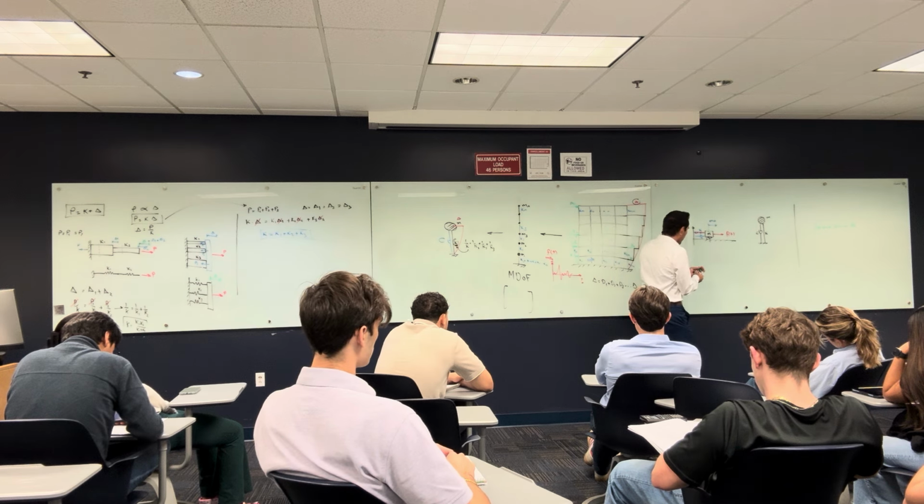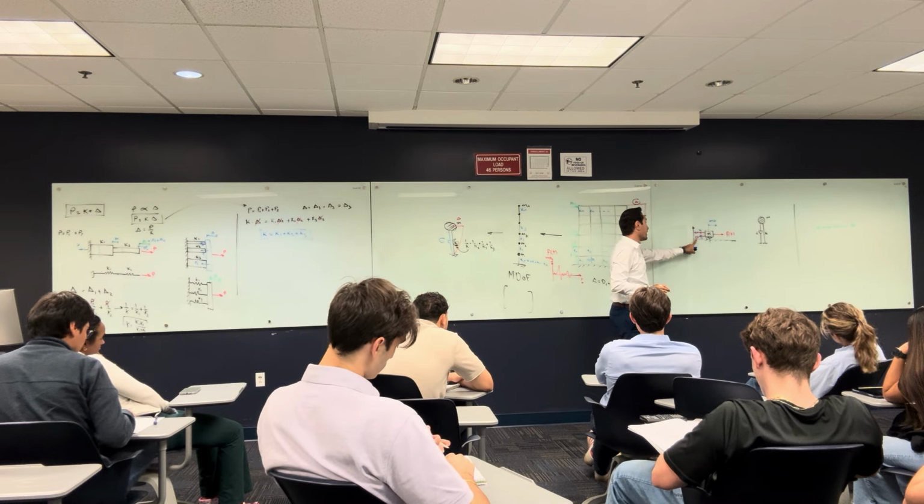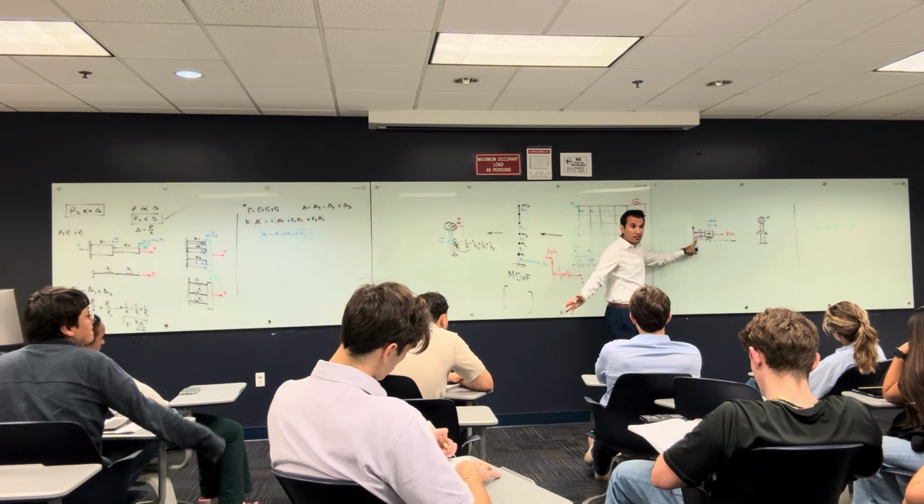The damping coefficient is gonna generate a force. This force is gonna be C multiplied by V because the damping force is always proportional with the velocity.